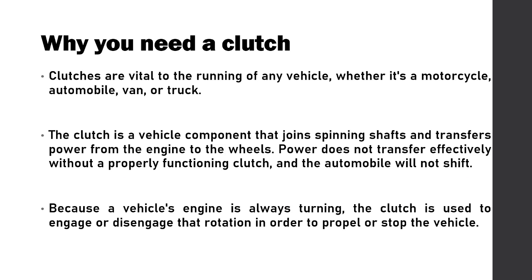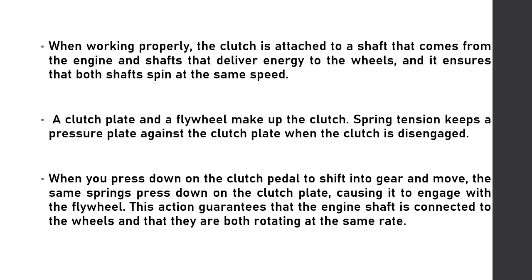Why do you need a clutch? Clutches are vital to the running of any vehicle, whether it is a motorcycle, automobile, van or truck. The clutch is a vehicle component that joins spinning shafts and transfers power from the engine to the wheels. Power does not transfer effectively without a properly functioning clutch, and the automobile will not shift. Because a vehicle engine is always turning, the clutch is used to engage or disengage the rotation in order to propel or stop the vehicle.